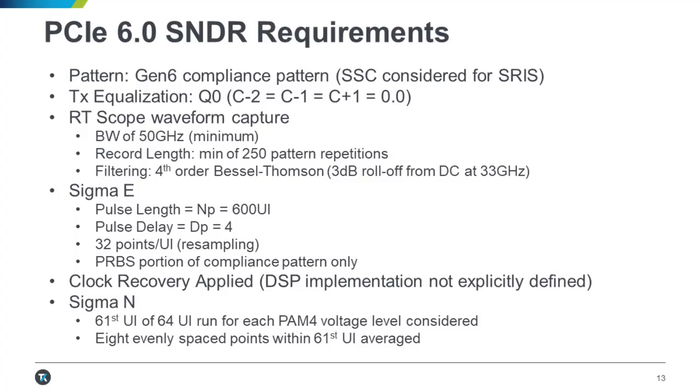So for the pattern, we have this new Gen 6 compliance pattern. It does have these low frequency sections of the waveform at all levels. We've got a long run length of 0s, 1s, 2s, and 3s for all 4 PAM4 levels. SSC does need to be considered in this measurement, especially for designs that will be supporting SRIS.